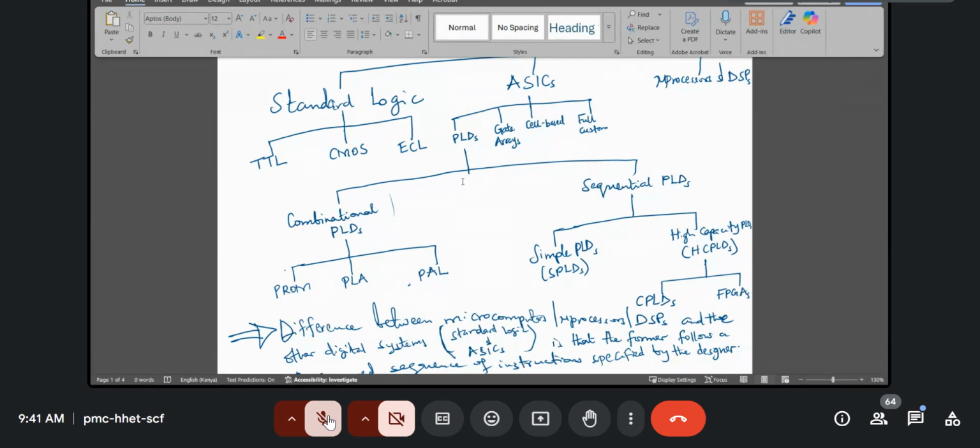For example, in the microcontroller world, I don't know the current kind of MCUs, and I don't know whether this is applicable to the Arduinos, but at some point when I was dealing with the Atmel devices, the Atmega series of MCUs, they did allow you to blow or program some fuses, which would decide how you would be programming that particular chip, because there were options of programming the chip.